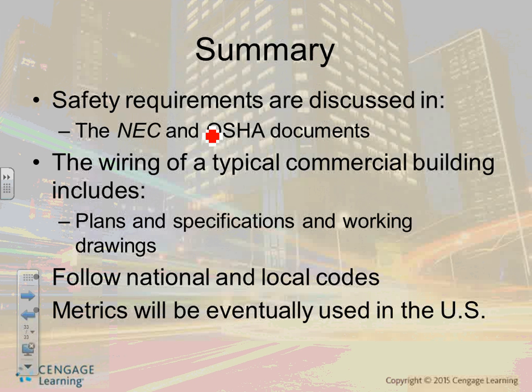Why? Because penetrating 4-inch concrete is different than a sheetrock wall, and it matters when you estimate. Or if you want to mount something like a transformer to a sheetrock wall, you have to be careful versus a block wall. Yeah, labor and hardware.